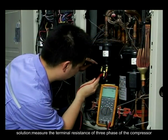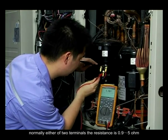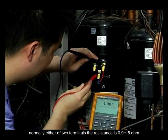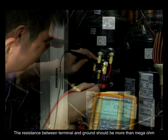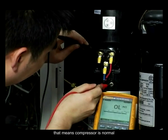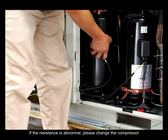Solution. Measure the terminal resistance of 3 phase of the compressor. Normally between either of 2 terminals the resistance is 0.9 to 5 ohm. The resistance between terminal and ground should be more than mega ohm. That means the compressor is normal. If the resistance is abnormal, please change the compressor.